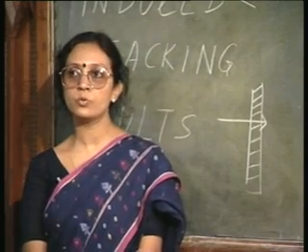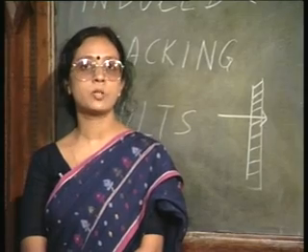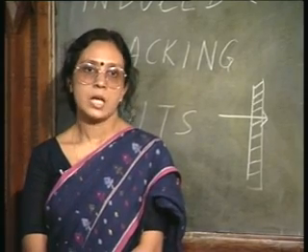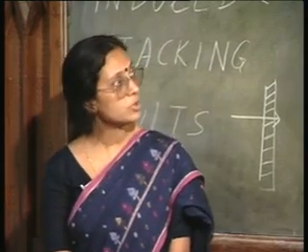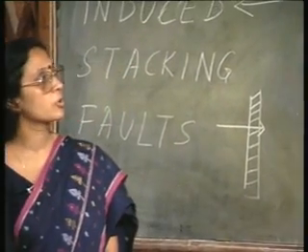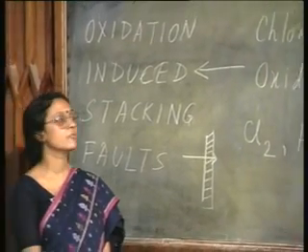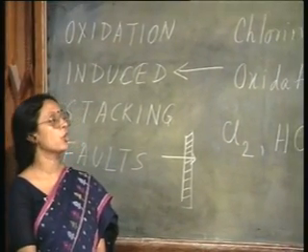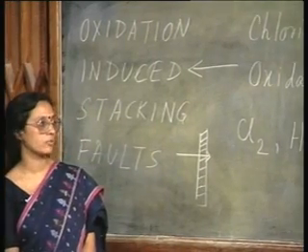They do not have to move into the defect site and cause the faults. They can be simply absorbed in these vacant sites and preserve the regular crystalline structure. So, it is found that a small quantity of chlorine during oxidation helps not only in fixing the mobile ions, but also reduces the oxidation induced stacking faults.